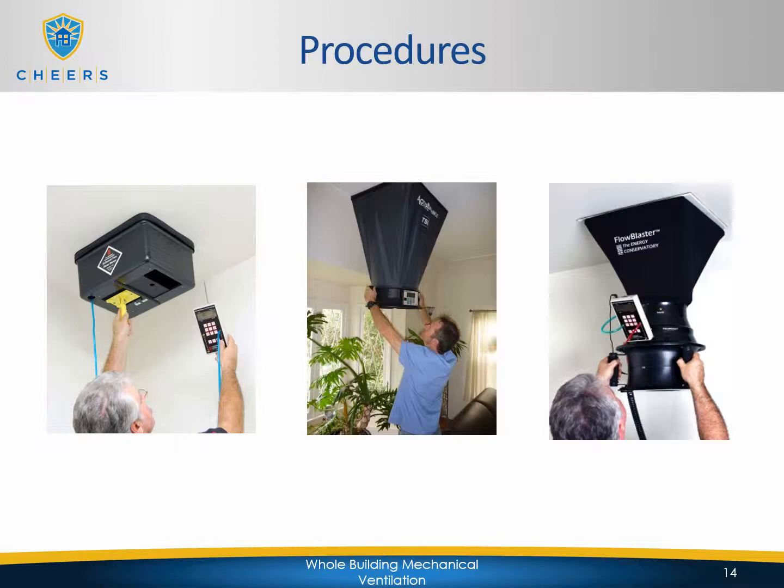And in these pictures you see the three pieces of equipment while they're being used. As you can see, each piece of equipment completely covers the grill that you're about to test. On the right hand side you'll see that on the very top the area of the flow hood doesn't quite cover the overall grill, because you can see the edges of the grill sticking out to the side. So that would be an incorrect way to test that particular system. The capture area of the flow hood, again, has to completely cover the grill that's being tested. So on the picture on the right hand side, even though that piece of equipment is correct, the way it's being tested is actually incorrect, and that would be a fail in that particular scenario.